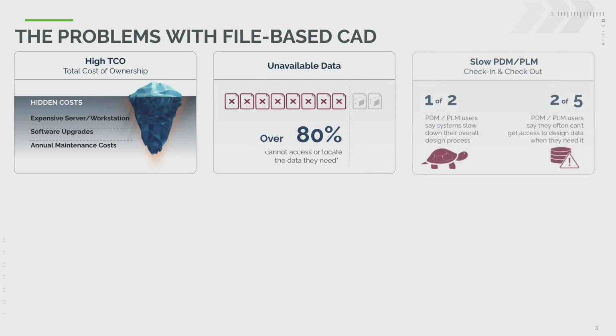and slows down the design process, which brings me onto the next topic. In the same survey, 1 out of 2 respondents were complaining that having a PDM system or even a PLM system actually slows down the overall design process, simply because there's an issue with accessing the data, checking it out, downloading gigabytes of data over a network locally to their machine, to fire it up in the CAD software, to do the design changes, to save it locally, to upload it back to the server, to check it back in. The whole process is very, very time consuming. So it slows the whole process down.